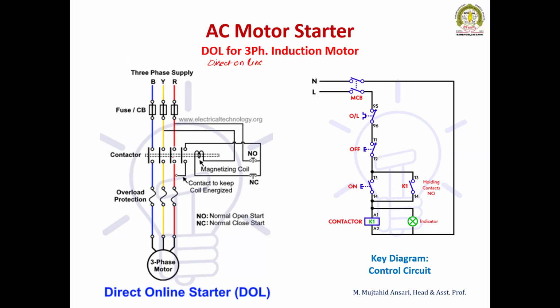So in the case of a three-phase induction motor, suppose the motor is connected in delta. The stator winding is connected in delta. This is the delta connected three-phase induction motor. And now we are applying the rated voltage VL between these two terminals. The impedance of this phase is Z1, this is Z2 and Z3. So consider the starting current at the time of starting, when the speed is 0.